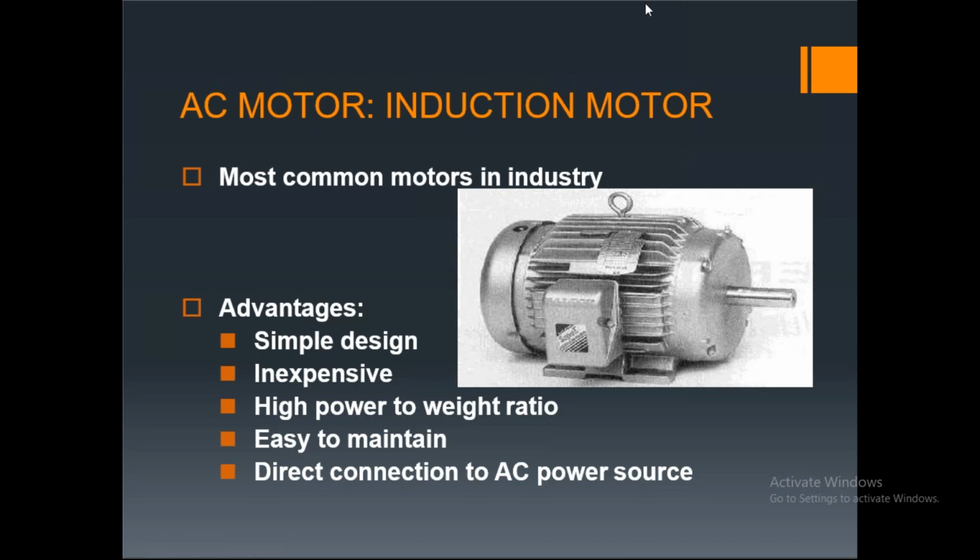Right. See, based on the supply, we have two types: single phase induction motor and three phase induction motor. Now, out of these two, we need to find which one is self starting and which one is not. The single phase induction motor is not self starting, for certain reasons I will explain later, and the three phase induction motor we can call a self starting induction motor. Now, how can we make the single phase induction motor self starting?